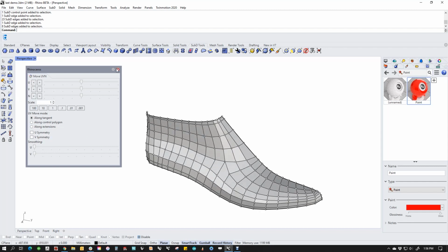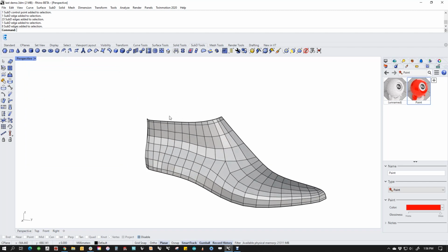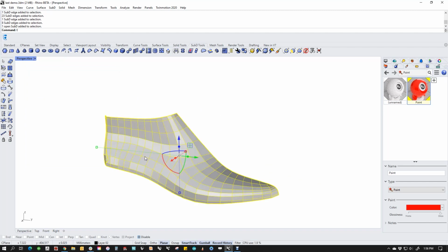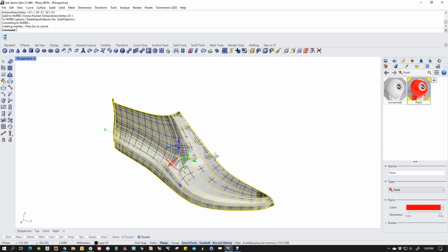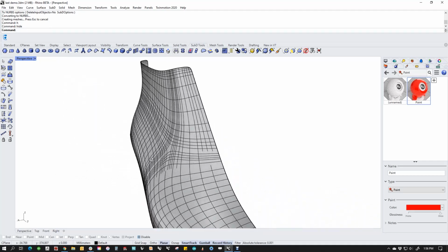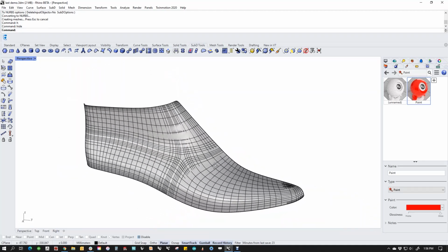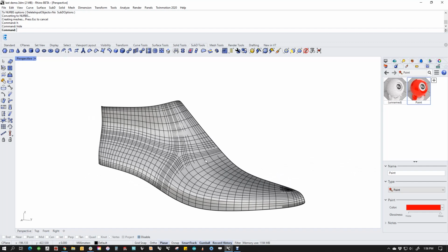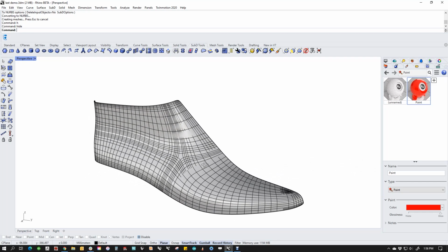Okay. So once we get to this point, we've got it fairly refined. Then what we can do is simply say to NURBS. And the sub-D options up here, we're going to pack these, and we're going to use G1. We could do G2 if we wanted, but G1 is fine for what we're doing right here, and we're just going to go ahead and run that. And the result is a beautiful surface, and it works off the sub-D, by the way. So if you're wondering why the sub-D was faceted and this is smooth, it works off of the limit surface of the sub-D, not the box version of it.